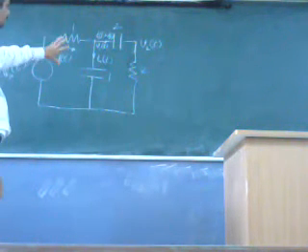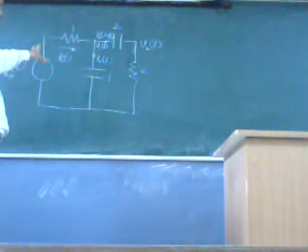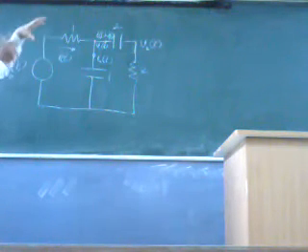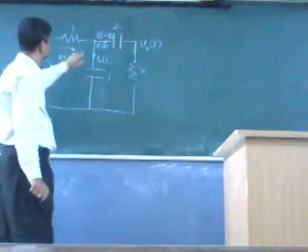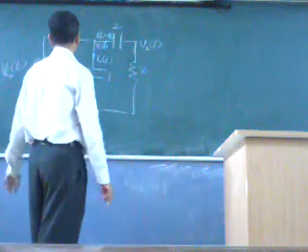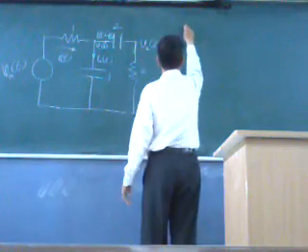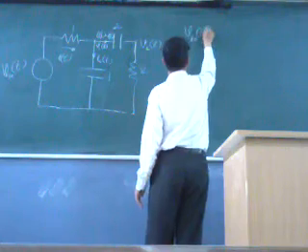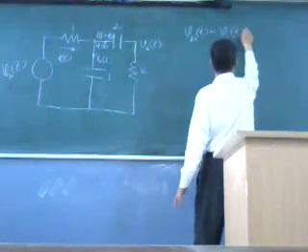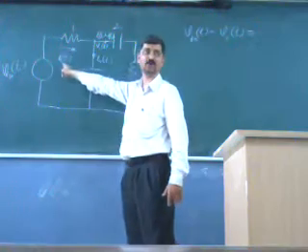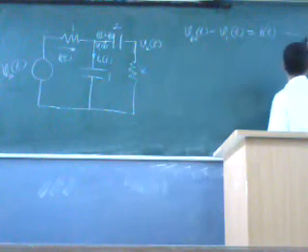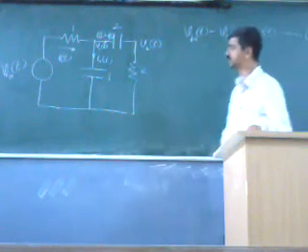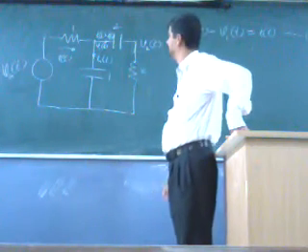So again we will have the same exercise. I will try to put the different relationship equations in assorted form, and we are supposed to club them up. The first equation which we can get is V in(t) minus V1(t) is equal to I(t), because R is 1. That is the first equation.